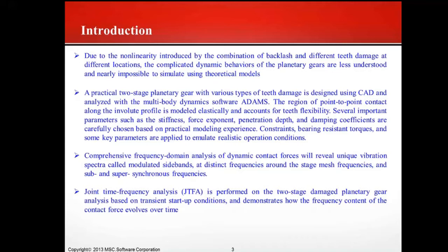For example, the stiffness, the force exponent, the penetration depth, and the damping coefficients, etc. In this way, we can very accurately simulate the dynamic behavior of the teeth of the gear.